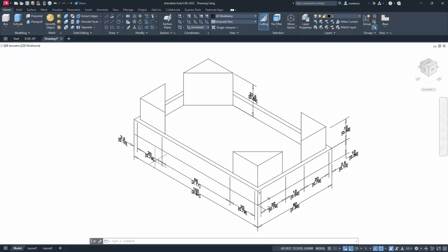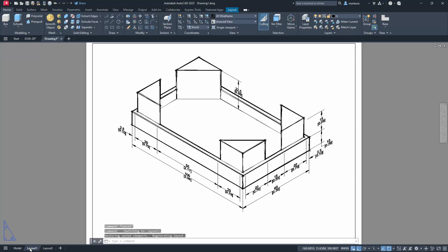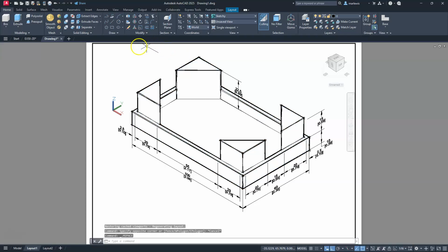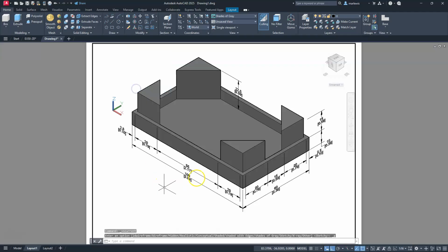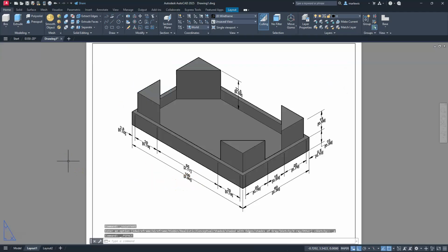Now we'll show you how to put these dimensions on. You will see one other thing here is that these are dual dimensions, meaning that I have the millimeter equivalent on top, and then I have the inches on the bottom of it. I'm going to show you how to do all of that, and you can see behind the curtain here that in the layout tab, you're actually seeing the drawing. And remember that we can control how this view looks, and we're going to get into all of this, and yours will show up here, but I can tell it how I want this to look in reference to my drawing.